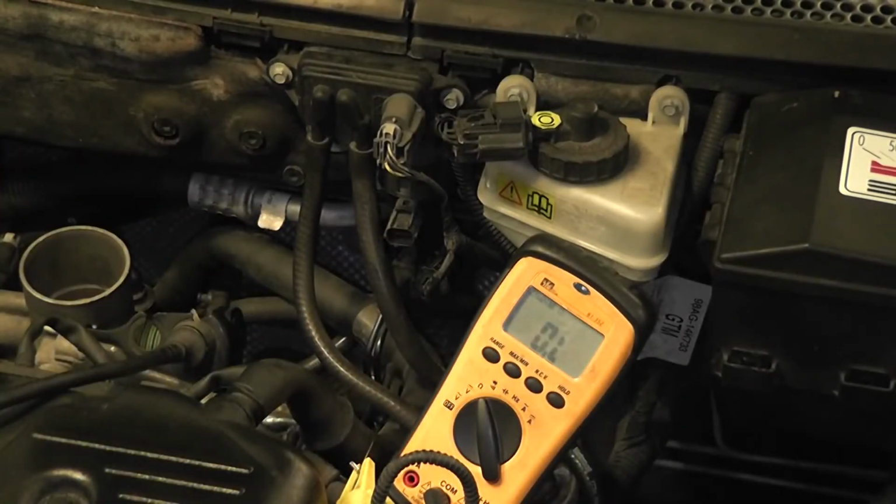The next thing that we want to do, we're not totally done with this. We want to make sure all the other components work on this car. And one of the things that I'm always worried about when I have an open solenoid is to make sure that the computer driver can still function. And a problem that you're going to run into as far as the driver goes is, with the solenoid out of the picture, because we can't use it to monitor voltage drops, we need a way to check this computer driver. We need a way to check the control wire and make sure it's not open.